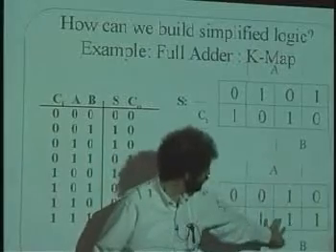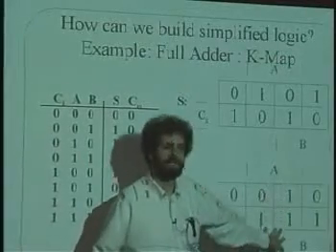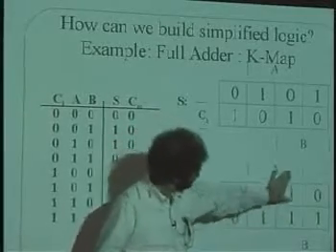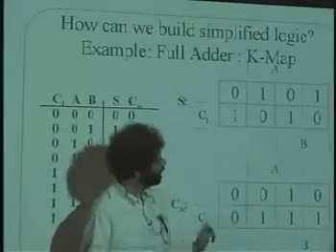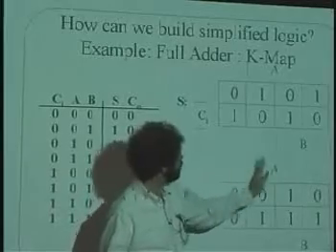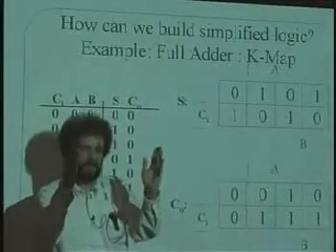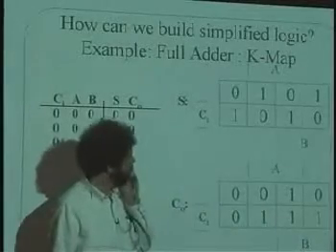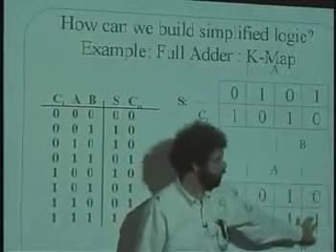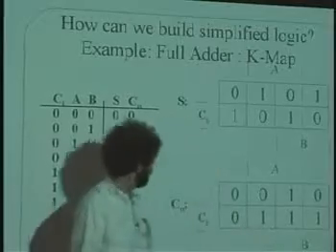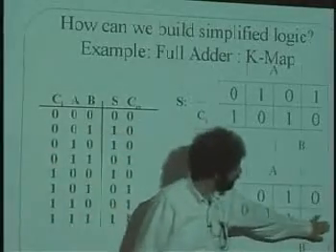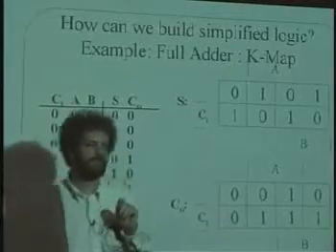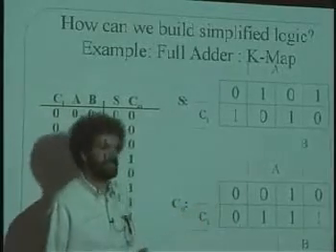In these 2 columns here are going to be the 4 cases where the input A is 1. This column here and this one here. And I'm going to denote that by saying A inside of these 2 bars. So in here, A is 1. And these 2 columns over here, B is going to be 1. And in this row over here, C sub I is going to be 1. That's pretty neat too. Now what's the characteristic that a checkerboard like this has?